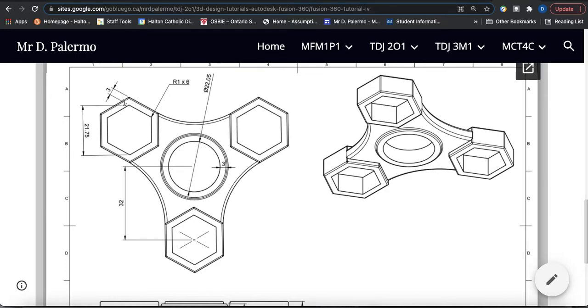Once I've done that, there's a tool in SketchUp that easily draws this hexagon here. Okay, so very quickly I will be able to draw these hexagons, and then I can offset these hexagons another 3 millimeters to get the outside hexagonal shape, right? And then all I'm using is just some arcs to connect my three sides there, okay? And then obviously we're going to be push-pulling.